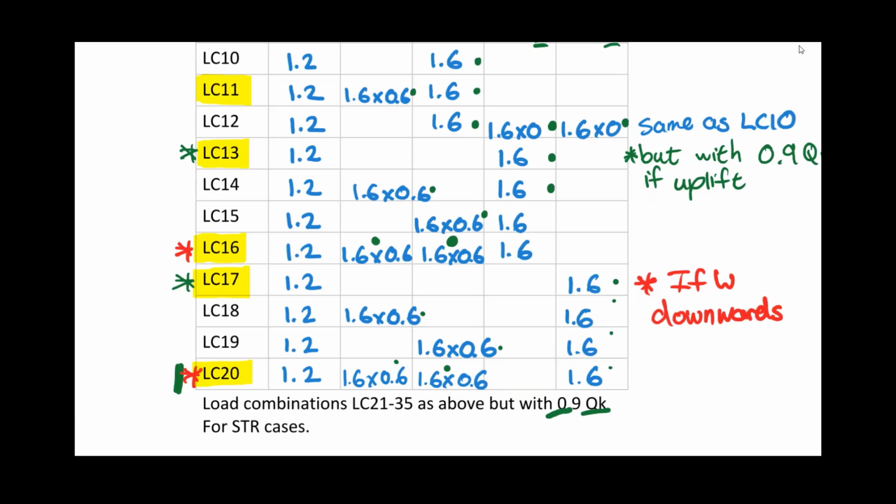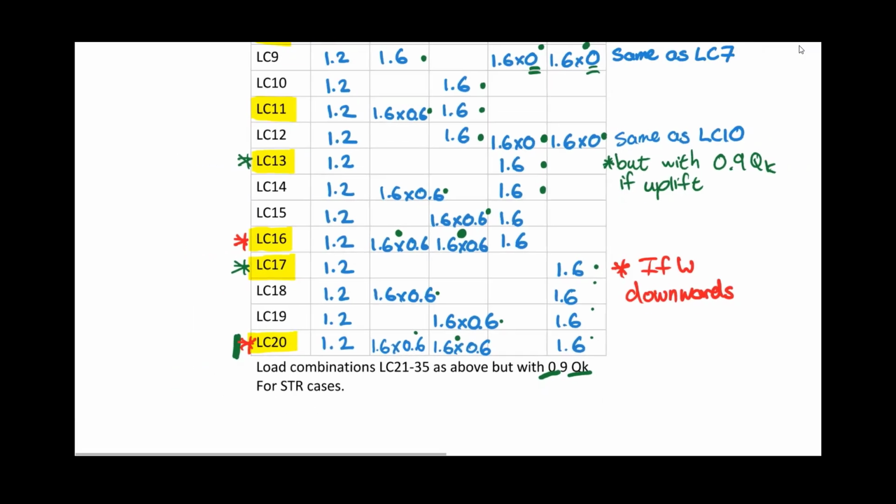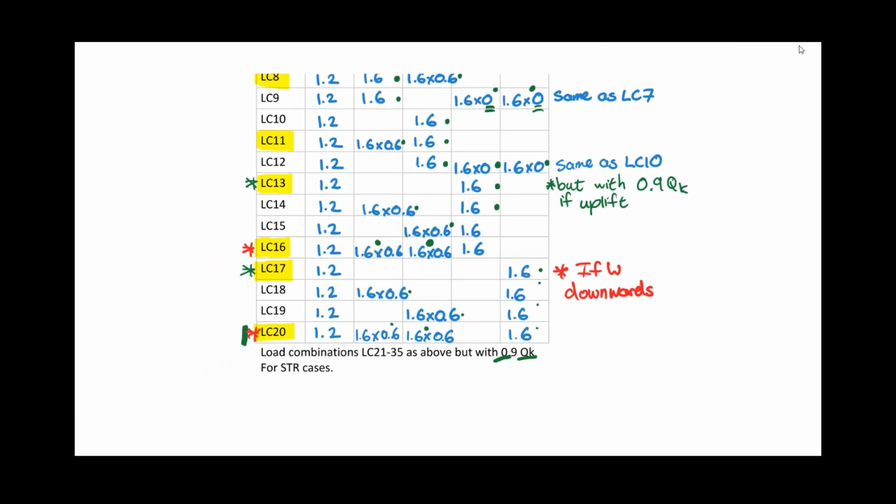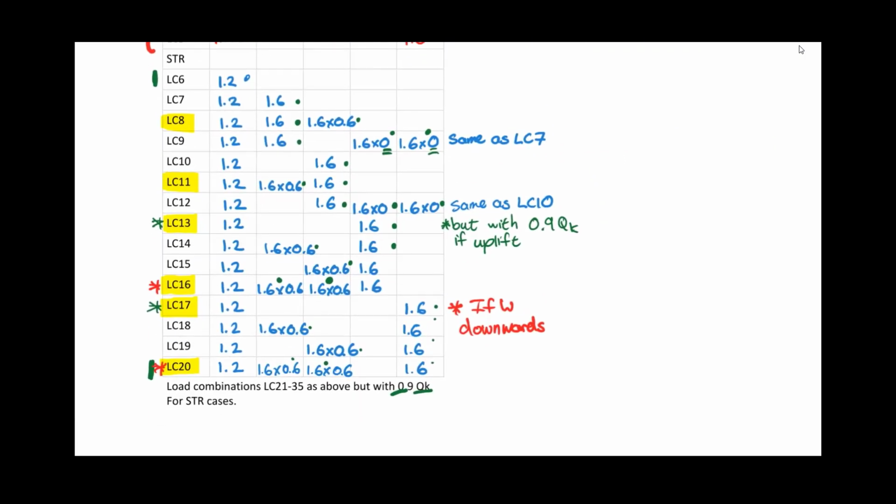If it's a net downward pressure, those are the load combinations likely to govern. And really, from 35 cases, we've reduced to a lot less than that, about 6 or 7, and very likely those would be what you would need to work with, but it would require some judgment.